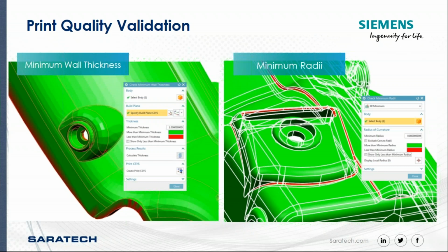And so you can put in those values here, the minimum wall thickness that your printer can handle, and check for those during design. So again, you're able to find these things as you're designing the part and make those modifications during the design cycle, which is much, much cheaper and more cost effective and time effective than doing that during the manufacturing process.